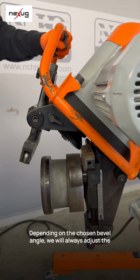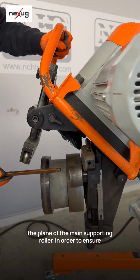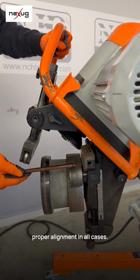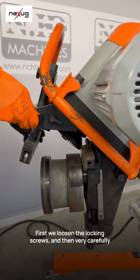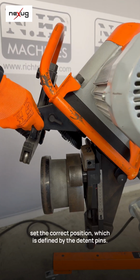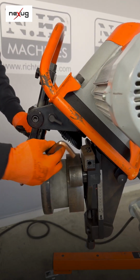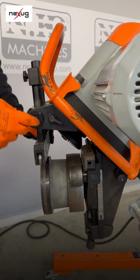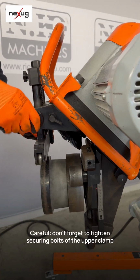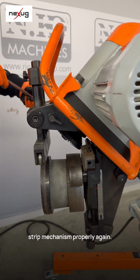Depending on the chosen bevel angle, we will always adjust the position of the upper pressing strip so that it remains perpendicular to the plane of the main supporting roller, in order to ensure proper alignment in all cases. First, we loosen the locking screws and then very carefully set the correct position, which is defined by the detent pins. Careful, don't forget to tighten the securing bolts of the upper clamp strip mechanism properly again.